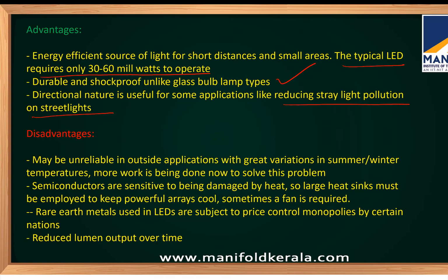Disadvantages: may be unreliable for outdoor applications with great variations in summer and winter temperatures, because the semiconductor materials are sensitive to temperature variations. Semiconductors are sensitive to being damaged by heat, so a large heat sink must be employed to keep the powerful arrays cool. Sometimes a fan is required. So heat sinking should be properly done, otherwise the semiconductor material may get damaged.